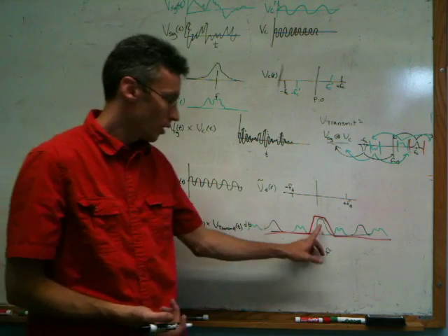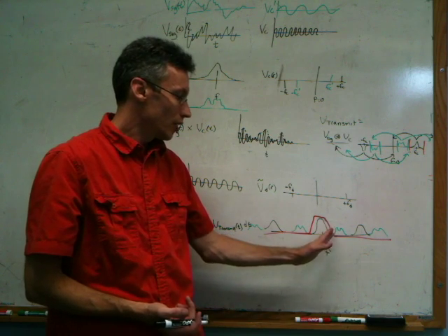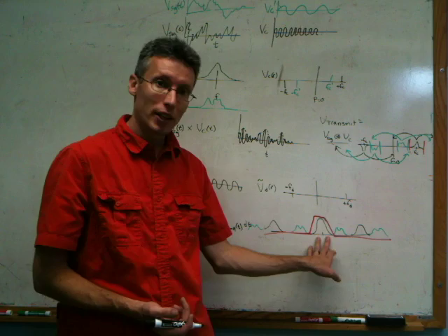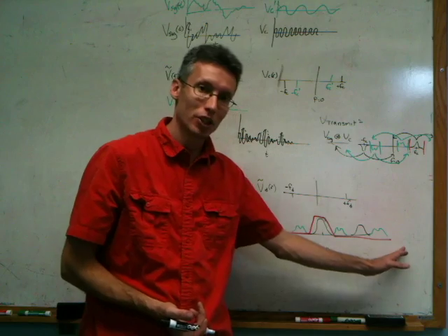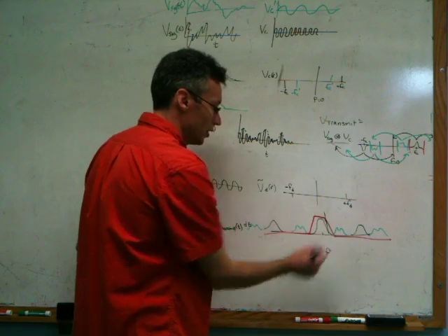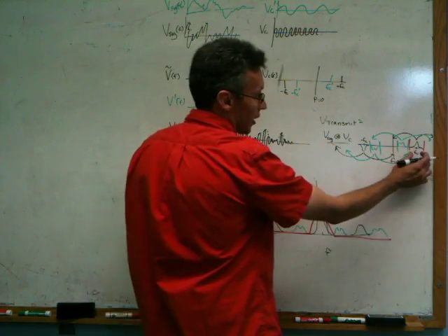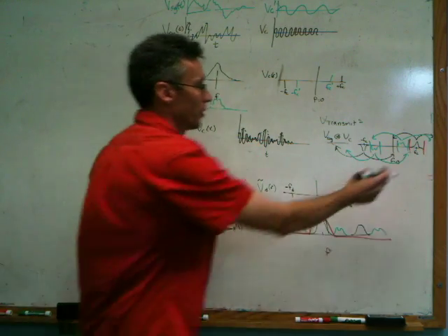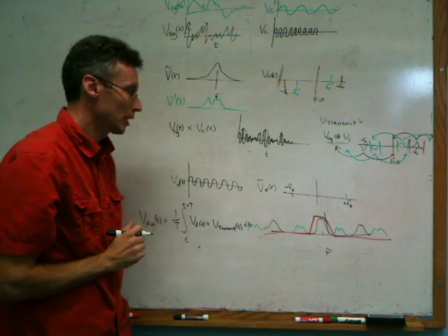And we choose the cutoff frequency of this low-pass filter such that it passes spectral content within my desired channel, but it blocks the neighboring channels. Okay, so the knee of this low-pass filter should be determined by the width of our frequency channels. Those frequency channels' width should be determined by the width of the spectral content we want to communicate.